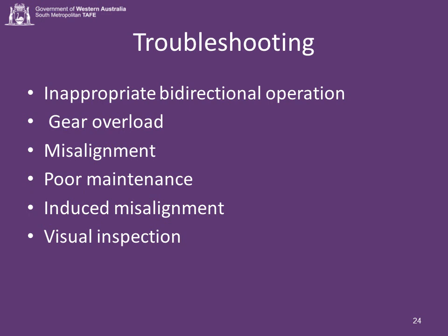Induced misalignment is also a common problem with gear drives. Most gearboxes are used to drive other system components, such as bridles or process rolls. If misalignment is present in the driven member, it also will directly affect the gears. The change in load zone caused by the misaligned drive component will induce misalignment in the gear set. The effect is identical to real misalignment within the gearbox, or between the gearbox and mated components.